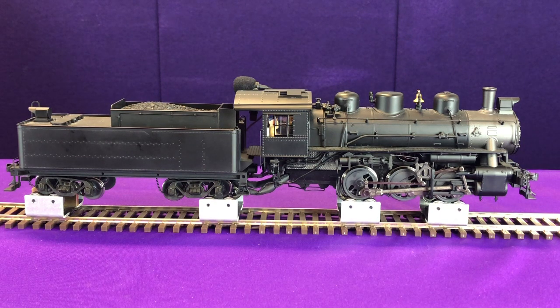We're going to set that to a value of 255 when the locomotive is running anywhere between speed step 20, 30. You can do it at speed step 10. The decoder will calibrate it, but we recommend around 20 or 30. And the reason is it gives you a little bit more distance between those points on this chart. Typically, if you run your locomotive at speed step 40, then calibrate it at speed step 40. So to do this, we're going to get going here at about speed step 25. So we have to wait a minute to let the decoder get to speed step 25.